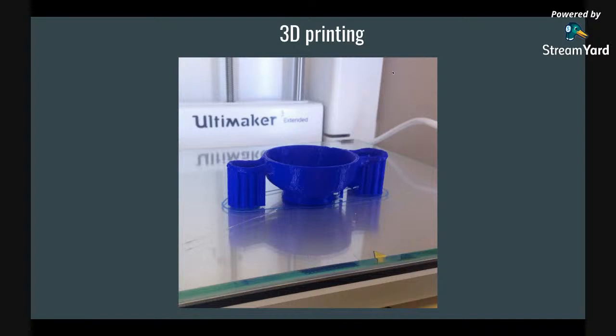And in this case, we have an image here of an object being 3D printed using an additive 3D printing method. And as you can see, if I tell you that this was originally a model of a Kylix, and that those vertical columns beneath the handles were not part of the original object, they're part of the printing process, because it's impossible to print additively an object, a part of an object that has nothing beneath it.